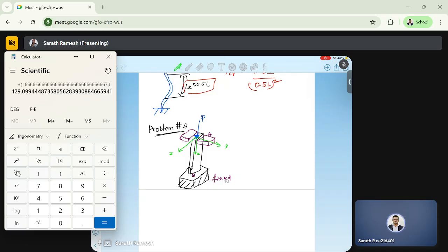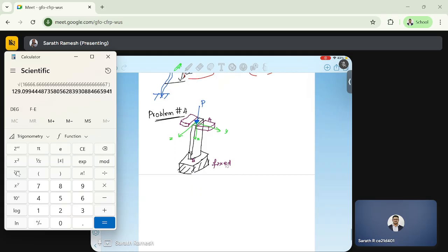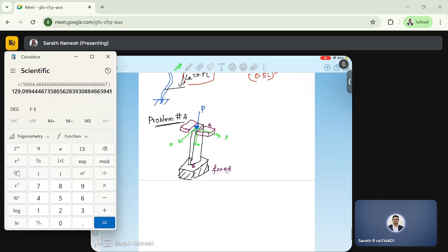So this aluminum column: two smooth and rounded fixed plates restrain end A from moving in one of the vertical planes of symmetry of the column, but allow it to move in the other plane. So here we see this cannot move along this y direction because it's restrained, whereas it can move along this z direction.